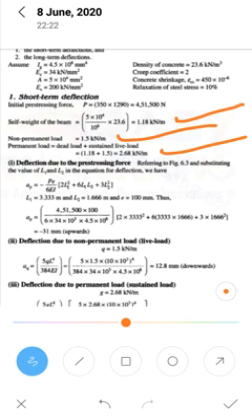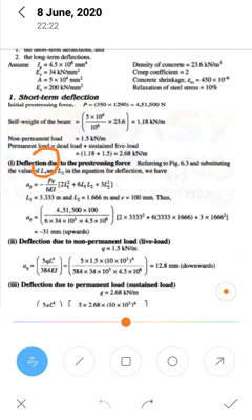Okay, next you will find out the deflection due to the prestressing force. They are given the trapezoidal section, with the tendons placed as a trapezoidal profile. Here the important ones are L1 and L2, so first you find out L1 and L2. L1 is given as 1/3 and L2 is given as 2/3.